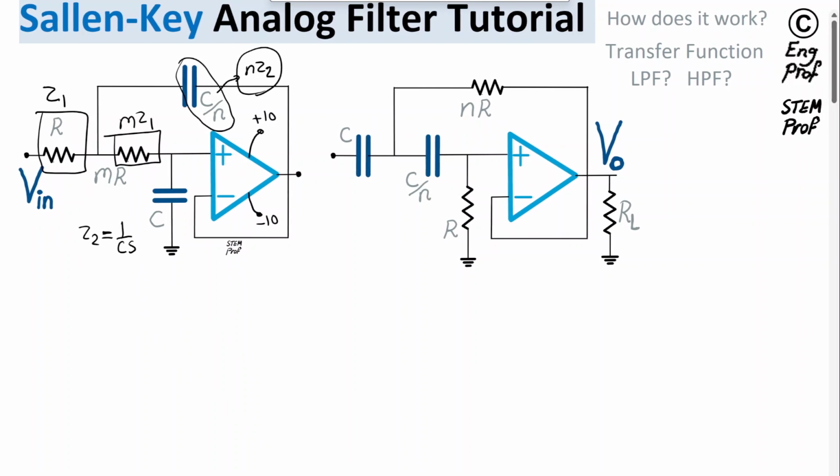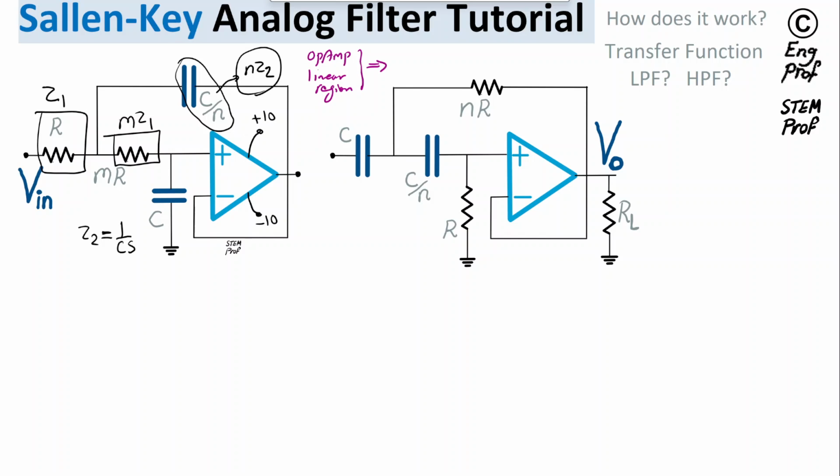Okay, so with that, op-amp is not saturated because of the proper biasing and negative feedback, in linear region of operation, and I can say for op-amp that is operating in linear region, I can say that virtual short is valid, which means the voltage at positive input terminal is the same as voltage at negative input terminal. Okay, so if the output is Vout, then via this wire, output is at negative terminal. So, and because of the virtual short enforced by the negative feedback, we should also have Vout at the positive terminal. So this node is Vout.